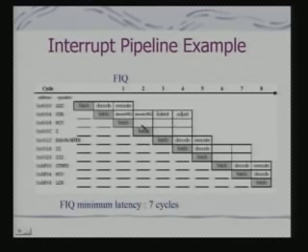This has been fetched, so I go to this point, and I am actually executing here. This is the branch instruction which gets executed. This fetch has already been done and has to be flushed, and then real execution starts from this point onwards. This is the first instruction of the interrupt handler. So, this is a scenario where you have a 7 cycle FIQ latency.